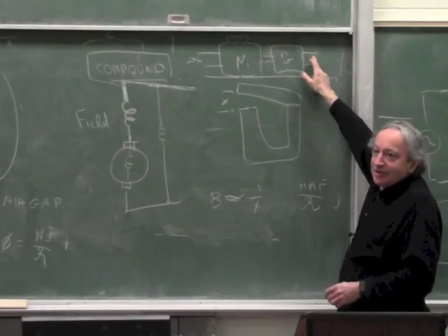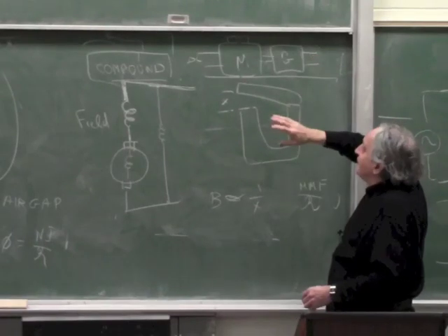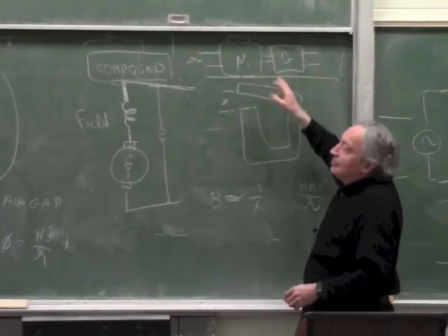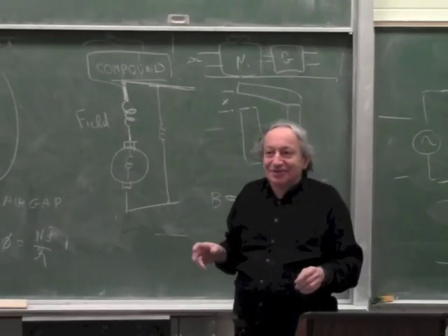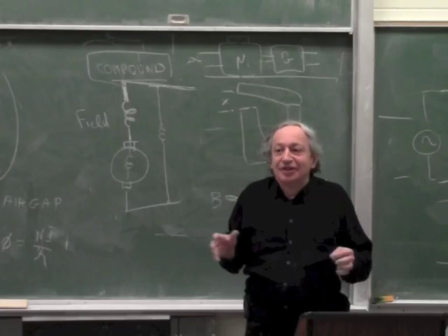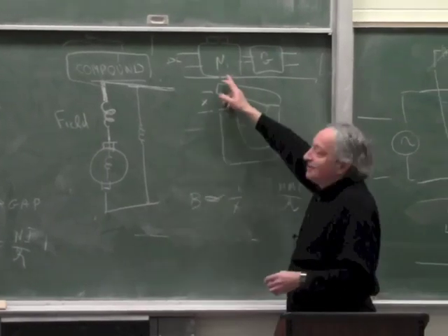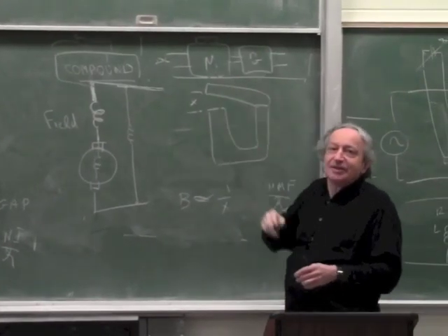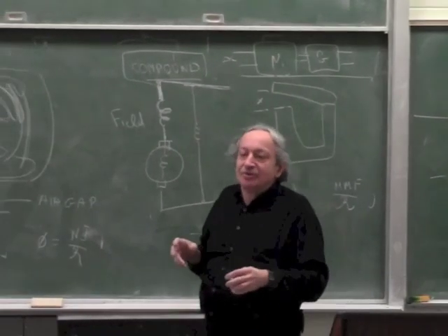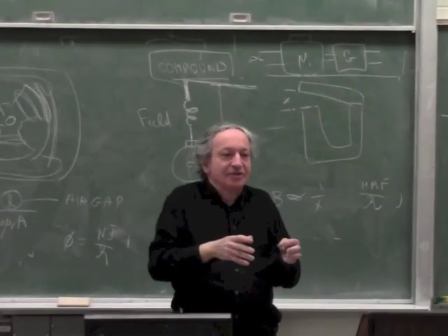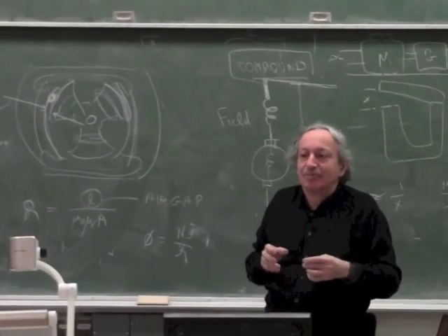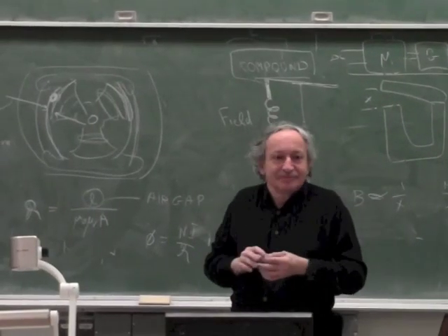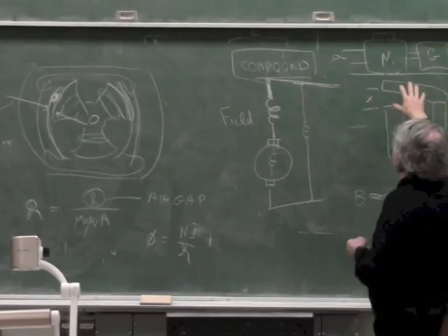So today when you look at it, it sounds crazy, but it turns out that this idea was the most popular power amplifier there was 50 years ago. There was no other way to amplify kilowatts except by doing this. Okay? So does everybody understand why a DC motor, or DC generator motor, when you control the field separately, is actually a power amplifier? Okay. This was called Ampli-Dyne.